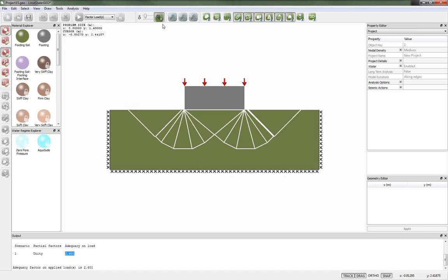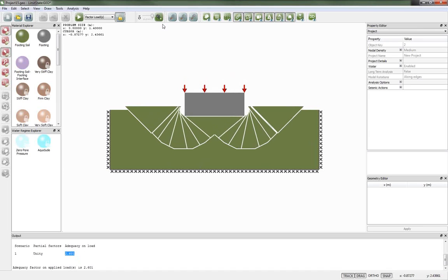Now the software, once it's identified the failure mechanism, animates it in order to increase the understanding of what's going on. Strictly, that animation is only valid at the instant of collapse, but it's taken further than that just for clarity. So you get instances of blocks of soil sticking out where they are overhanging, but that's just a matter of the animation being taken beyond its limits of validity.